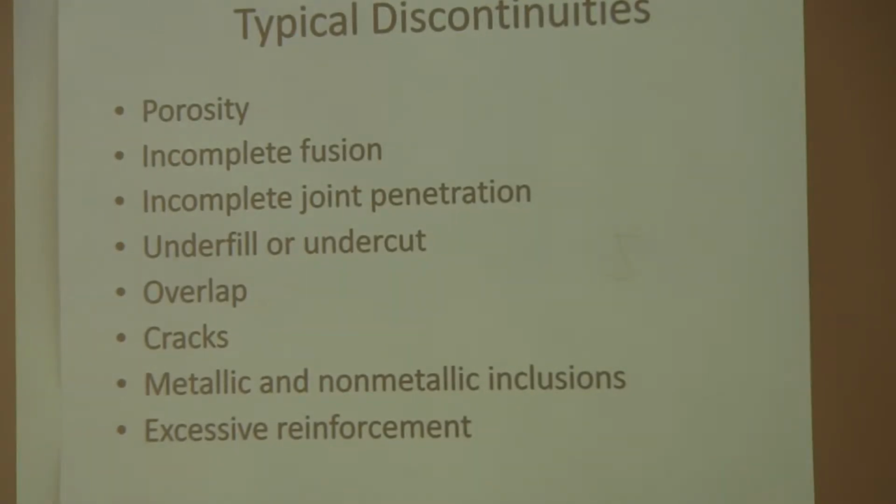So when he's looking at the surface quality, since a weld inspector is only looking at surfaces, he's not actually using other NDT techniques. He can ask for other NDT techniques like X-ray or ultrasonics, but when he's doing his inspection, he's just looking at the surface, and so he's going to see things like porosity, incomplete fusion of the weld, or incomplete joint penetration of the weld.